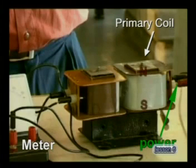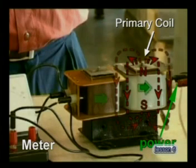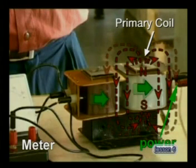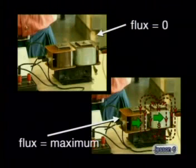When the switch is closed, current starts passing through the primary coil. Remember, a current passing through a coil will produce a magnetic field. This magnetic field will magnetize the soft iron core that passes through both coils of the transformer. So a magnetic field builds up around the transformer. This means that the magnetic flux changes from 0 when the switch was off to a maximum value just after the switch was closed.